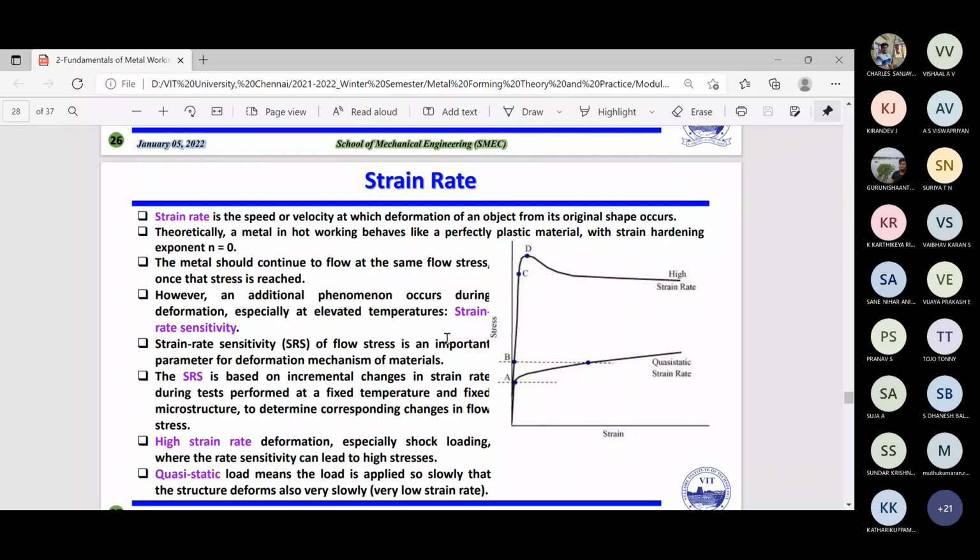Okay, because yesterday we were talking about how to remove the stress, somebody was asking, or maybe what we were telling about the heat treatment. Of course we have to do the heat treatment, there is no other choice. But depending upon the material behavior, for example, if you talk about stainless steel, you have to go for a higher heating temperature, maybe around 500 to 600.